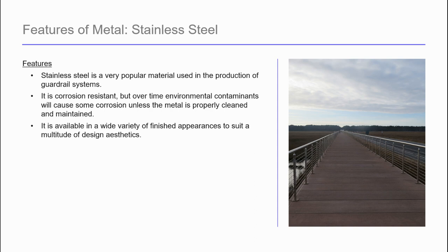It's generally the most widely used in architectural applications, no doubt, because of the appearance. People like that stainless look. Don't have to paint it. You shouldn't paint it, in fact, because the stainless is a nice finish all by itself. The one thing to note about the way that it has to be treated is it's a process called passivation. That's just a note that you should keep in your head. Doesn't mean you need to know a lot about it, but it really provides long-term corrosion resistance when that material is passivated.